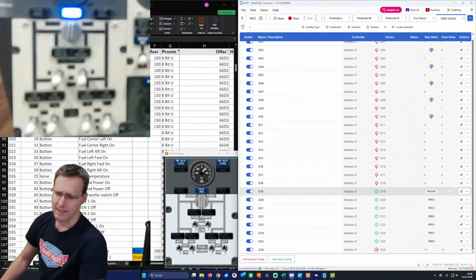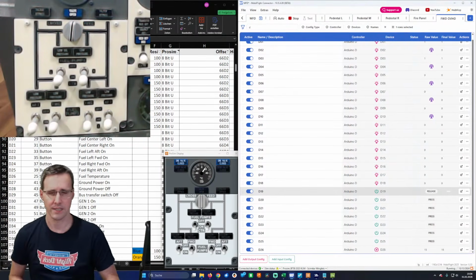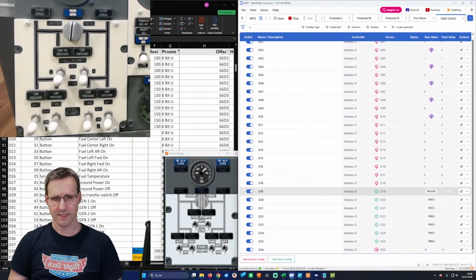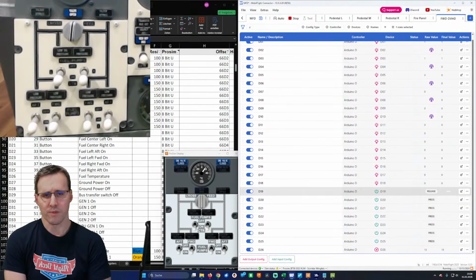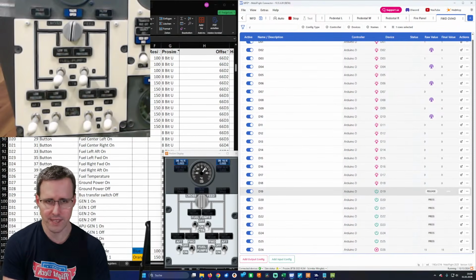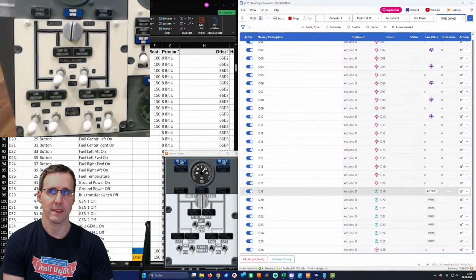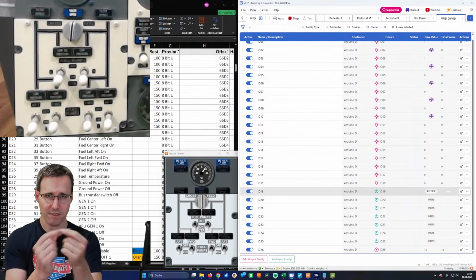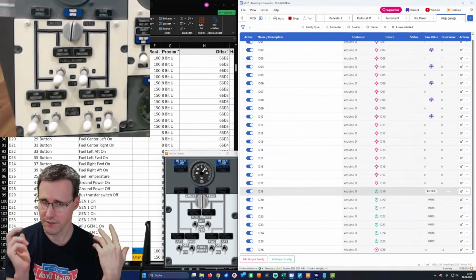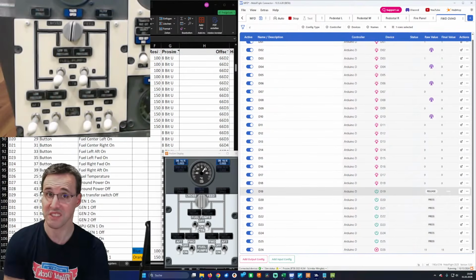Yeah, this I will check here separately, because this is a really weird construction here, simulating a 4-position switch with an 8-position switch. I have to make this somehow electrically, that I shorten together 2 pins of this switch, and they both send the same signal.